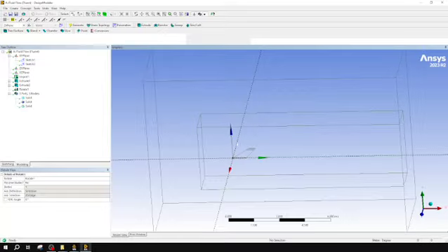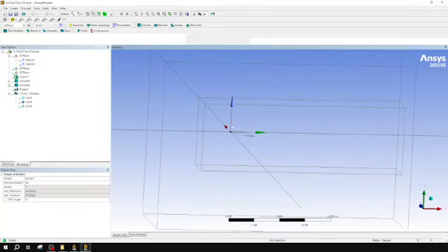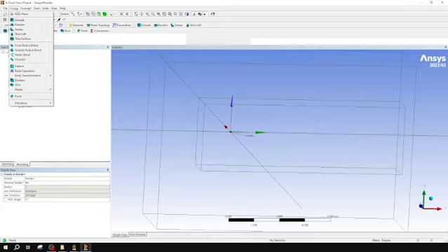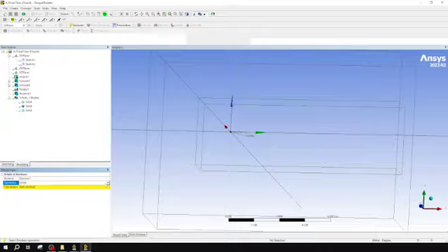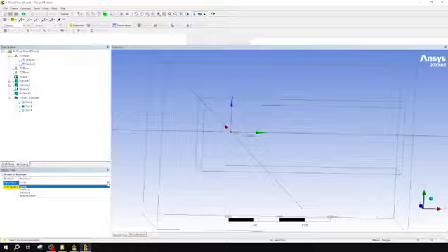So now that I got kind of my wing able to rotate, my box is set up, the last thing I'm going to do is go back to my Create, and this time I'm going to make a Boolean. For this Boolean, I am going to not unite. That would be adding 2 things together. I'm actually going to subtract.